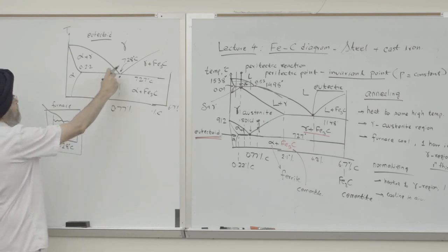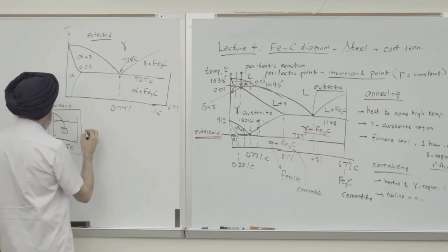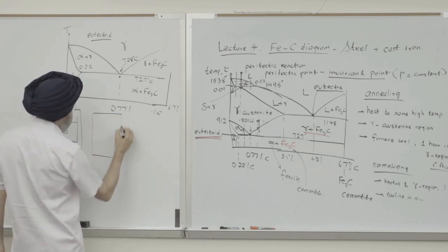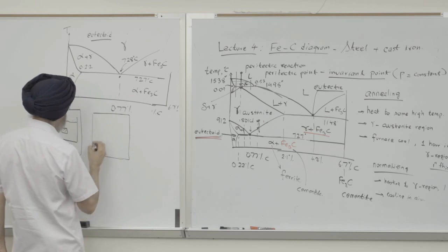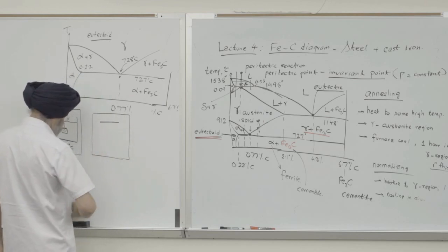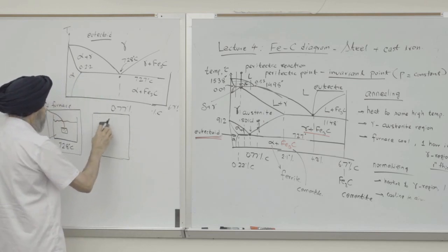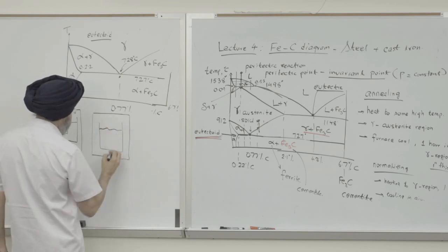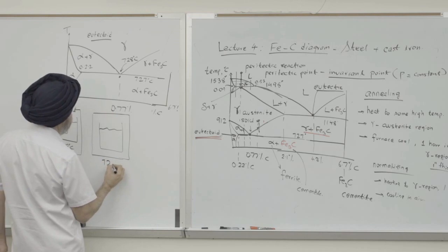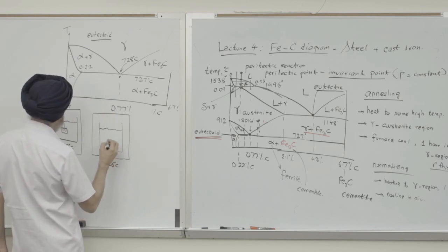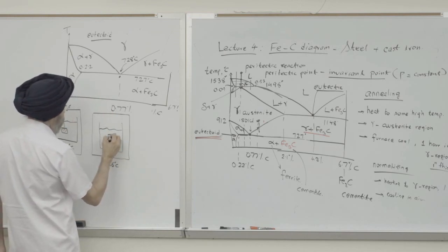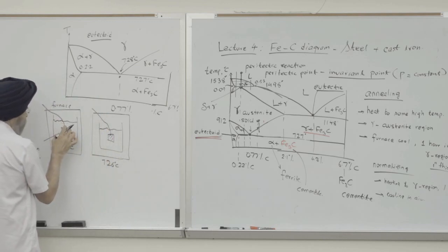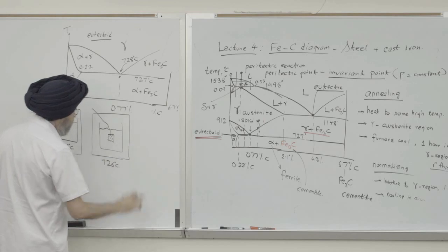We want to study this reaction. So he has a second furnace ready to go with a molten salt. You could use the same salt, and this is held at 726 degrees centigrade. So what he'll do is he'll transfer the steel from here to there.